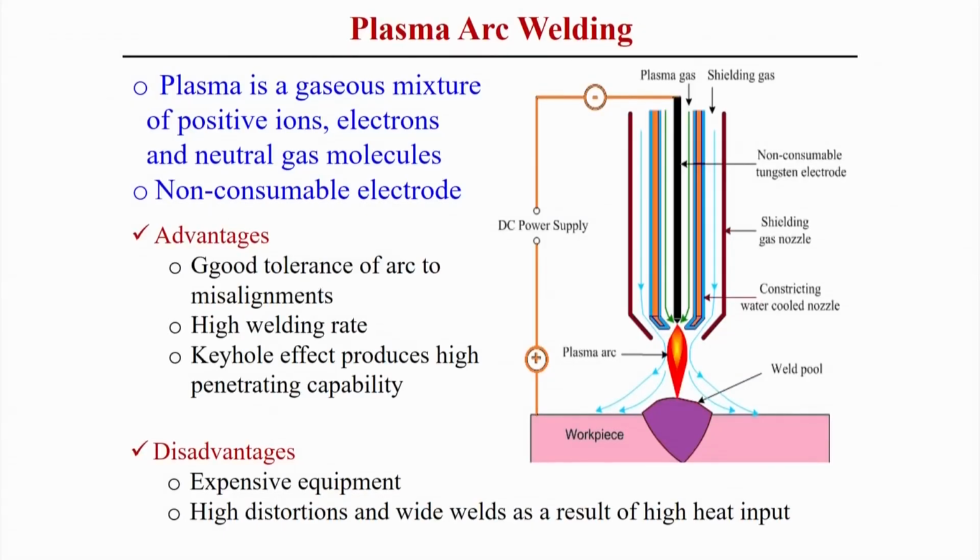With this controlled current, the arc can also be controlled in pulse or continuous mode, and that small amount of current indirectly controls the heat input, and the heat input can be created in a very small amount that may be suitable for any kind of micro welding processes.